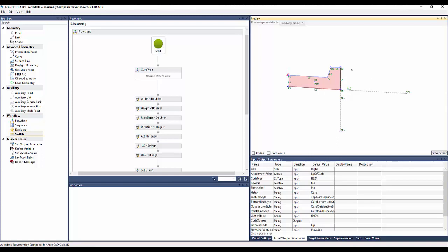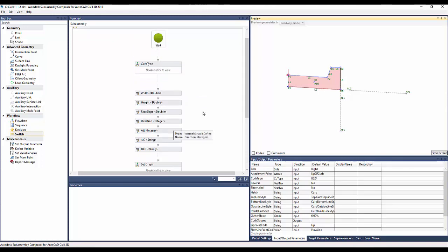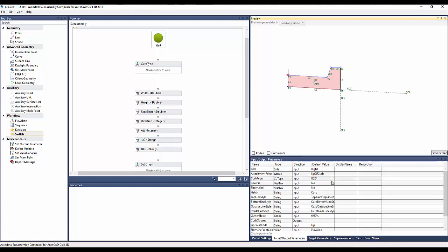As we take a look, this is very similar to that ultra simple subassembly that I had on screen earlier. If we look down, it's a little more complicated, and part of the reason for that is that this has essentially every curb that MnDOT, again I'm from the other side of the river there, has, selectable from this particular dropdown. So you can do all the different B curbs that are easily available across the board. And as we change some of these, you can see it follows the plate exactly, and you shouldn't have to change any of the other variables as you're going through.